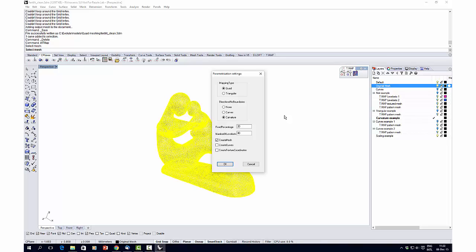If you select curvature, it comes with an additional option to influence the results, which is this fixed percentage option. They come together. The fixed percentage parameter indicates what proportion of the initial surface should be used as influence. This is arguably the trickiest parameter. There's no good solution that will work in every case.